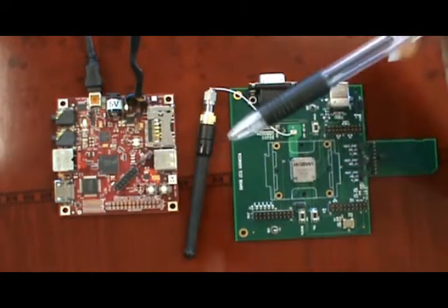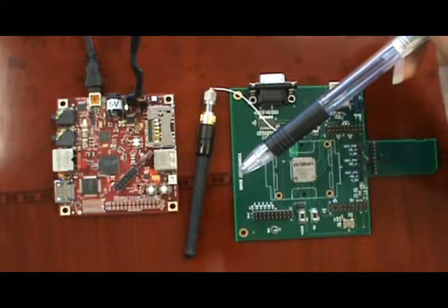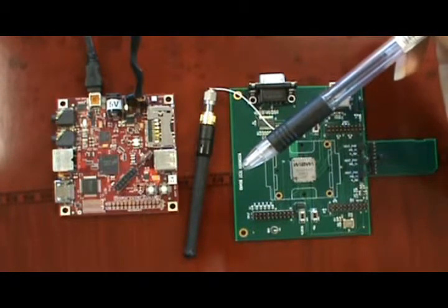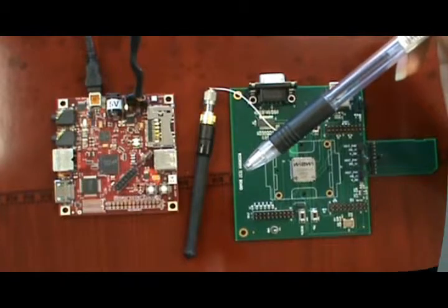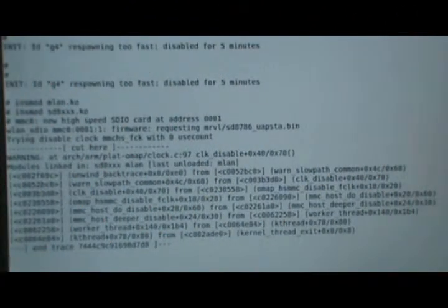There is a serial port that can be connected to a notebook computer and used as a console for the Beagle board, using an application such as Hyperterminal or a Linux-based laptop with Minicom support. We will assume that the Beagle board has been flashed with Linux. The user interface console is shown, which allows us to interact with the operating system.